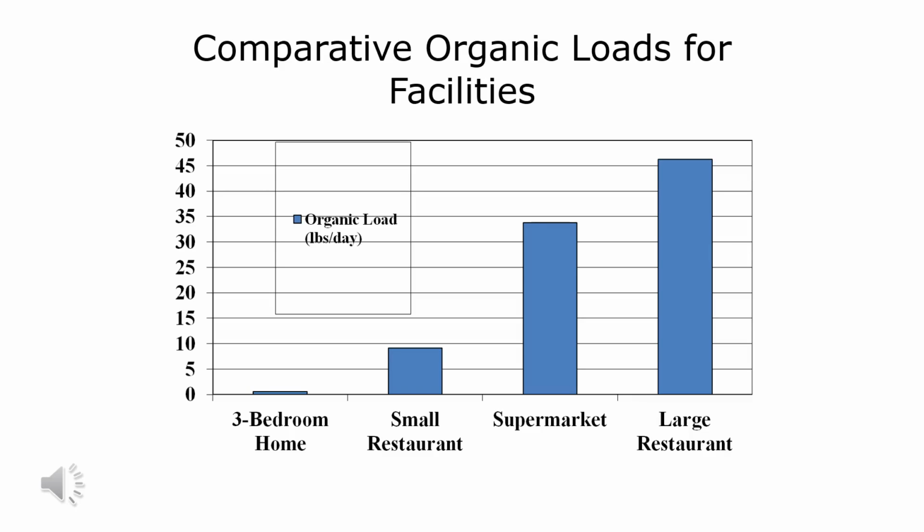High-strength wastewater has to be pre-treated to have many pounds of BOD, TSS, etc. removed to the point that the wastewater that you're treating resembles domestic wastewater. Then those more typical processes will work.